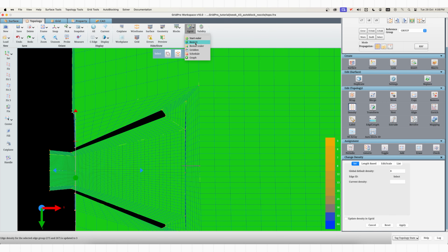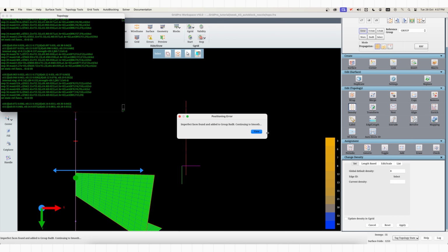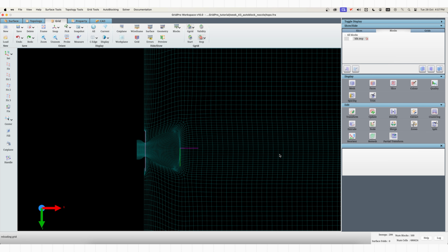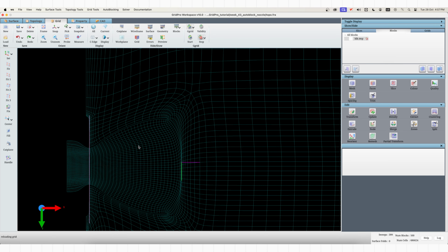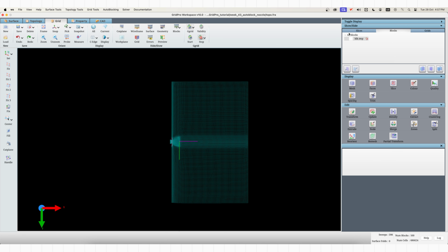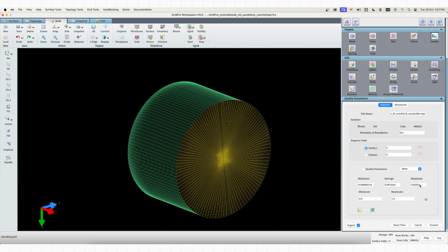The grid can be restarted from the existing grid to reduce the overall grid smoothing time. Update the grid to see the reflected changes. As can be seen, the grid is visually smooth and captures the nozzle features precisely. The max skew got reduced to 0.82. Running the grid further helps in smoothing the regions of sparseness.